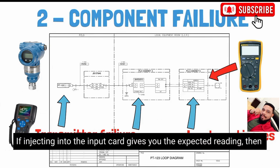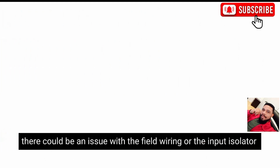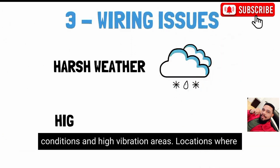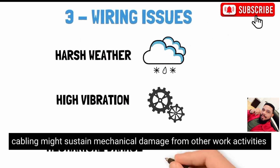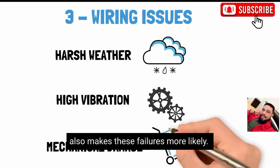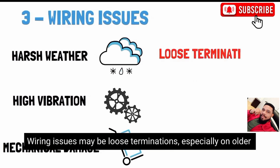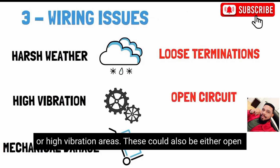If injecting into the input card gives you the expected result, there could be an issue with the field wiring or the input isolator. This is more common in harsh weather conditions and high vibrations. Field cabling might sustain mechanical damage from other works, which also makes this failure more likely. Wiring issues may be loose terminations, especially in high vibration areas.